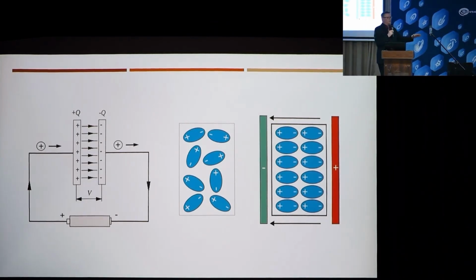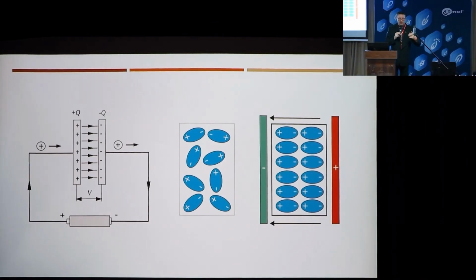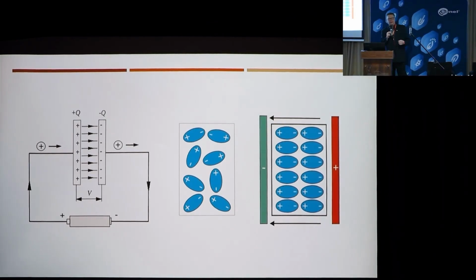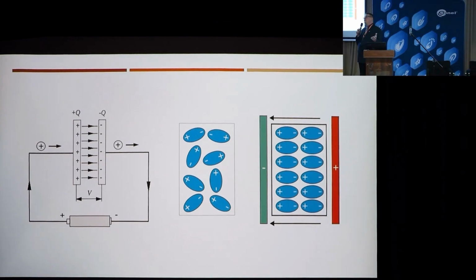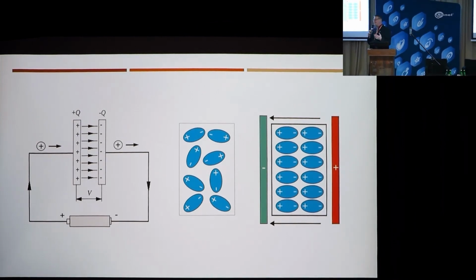And just as an aside, speaking completely generally here, I've also run into situations several times where a supervising inspector demanded that a specific result be entered because if it says more than 2 gigaohms, then he doesn't know what that means. Well, ladies and gentlemen, if the required insulation resistance is 1 megaohm and the meter shows more than 2 gigaohms, then that's good, isn't it?